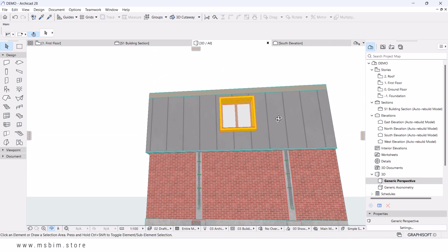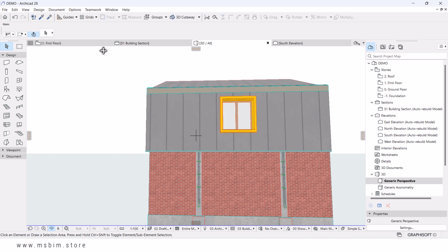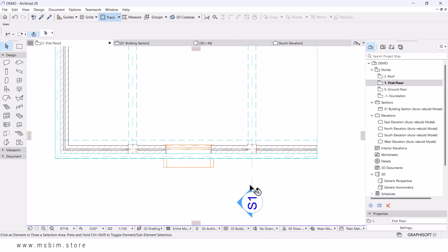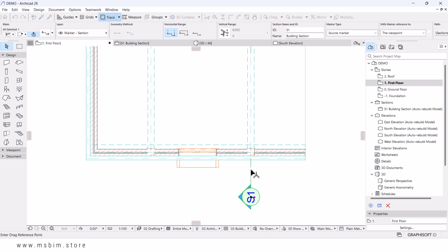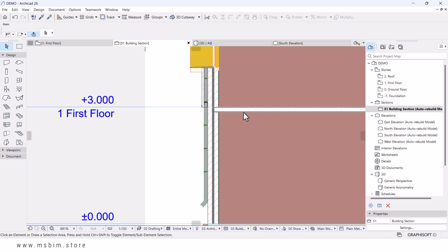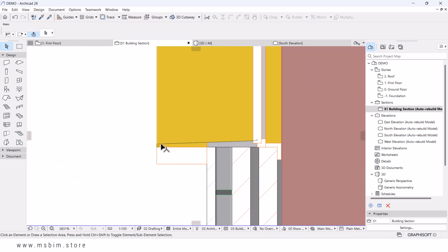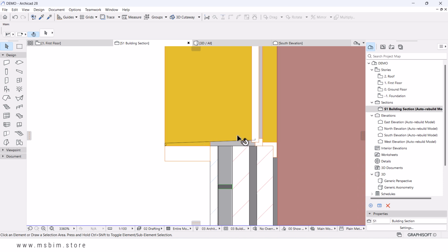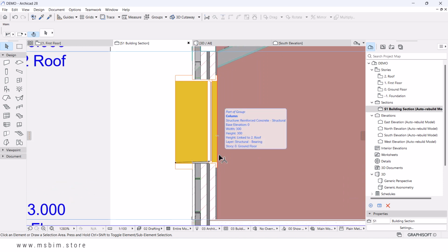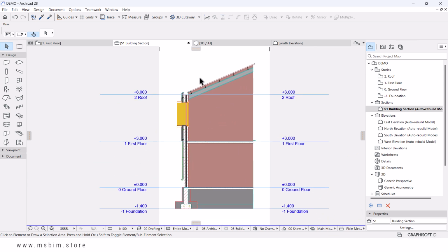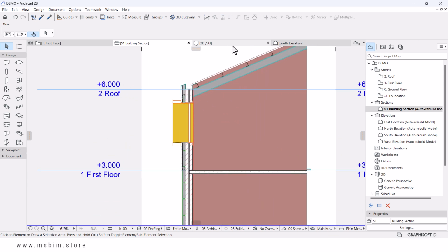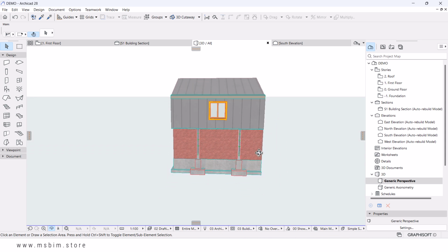Right, so my section is going to cut right through this window. So I'm going to cut it like that. So if we check on 3D, this will be exactly the same thing. See, this is now my metal seal that is a bit slanted so that water doesn't really stay there when it rains. Perfect. Okay, yeah, pretty much everything is in place now.